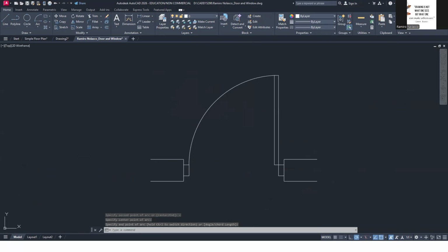First of all, you might want to move it down. So move to way up here. Okay? Move like this. Down. And start. Yeah. And then hinge. Wait. Before you say hinge though, you say arc, start point, and then you have to say center, and then define the center because it's asking for the second point. So you want the center and then the end point.